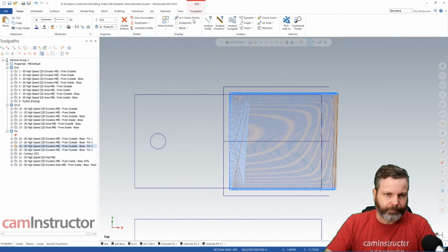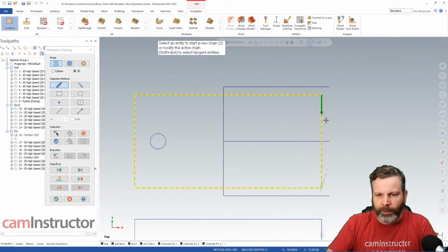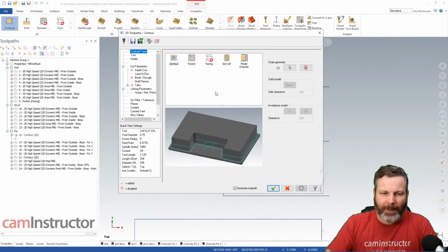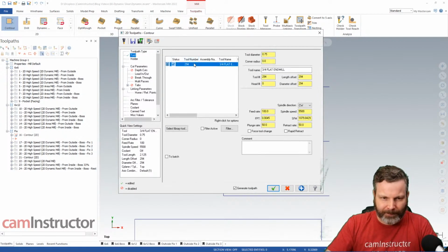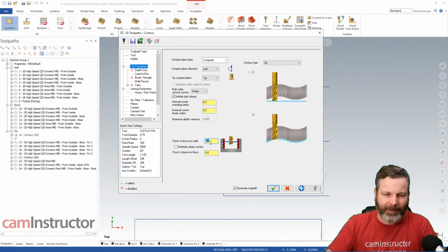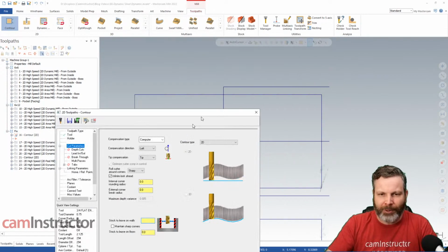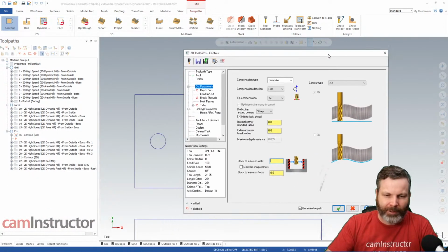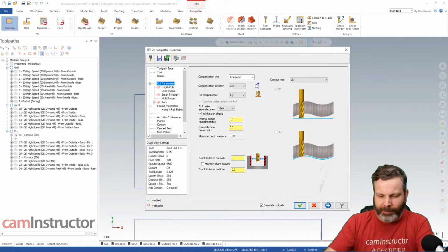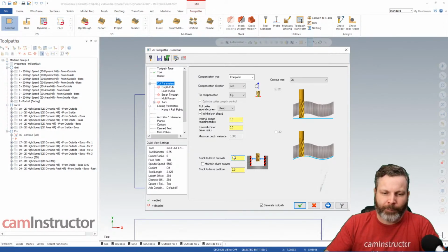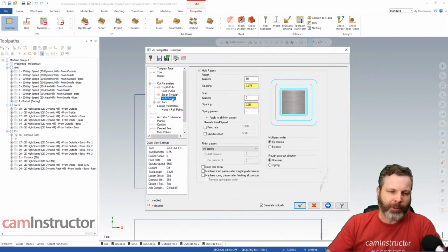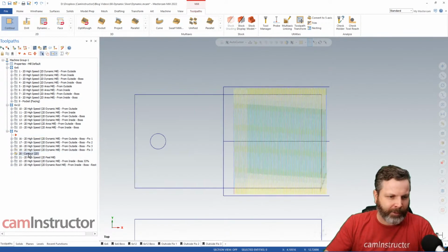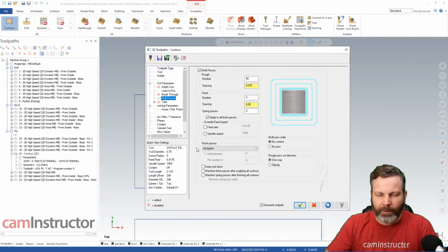You can go old school, grab a contour, hit this one edge, chain one thing. The problem with the contour is we have to calculate how much stock we need to leave. So if I'm chaining out here, how much past that do I want to machine? I had a -6 in there, so let's just go with that -6. And if we did this, we still now need to come in and calculate multi-passes, which I think I've already made this toolpath before, so let me hop into that. I've got it down here. There it is. Okay, so the problem with contour,